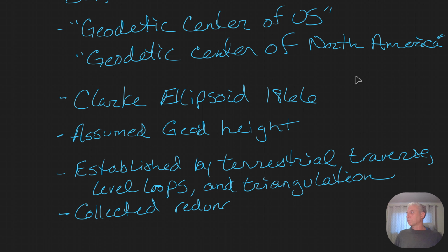redundant measurements. Now, a lot of you have not had least squares adjustments, but we really dive into redundant measurements. It just means repeat measurements, right? Or getting observations out in the field that we could otherwise just compute. So if I have a point and then a distance and angle to two more points, that suffices to get the triangle, but I would be computing that third side, right? So measuring that third side is what gives me redundancy.